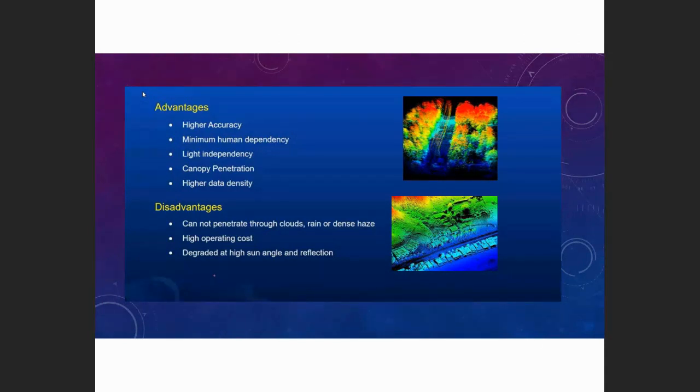Even the processing, I will show you how easily I can process the LiDAR data sets. Then light independency: it is not required to be daytime only, you can do the survey at any time. And canopy penetration is another advantage of LiDAR.